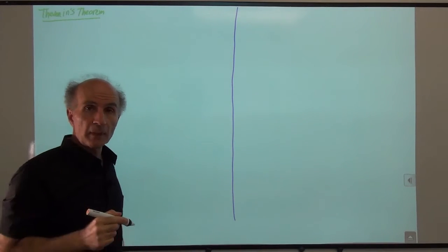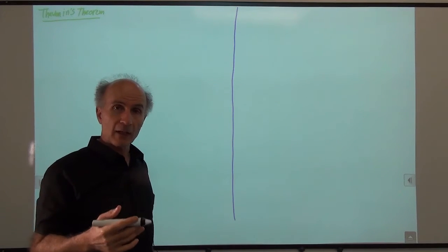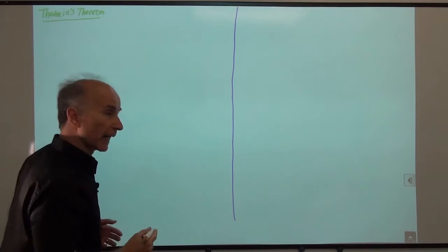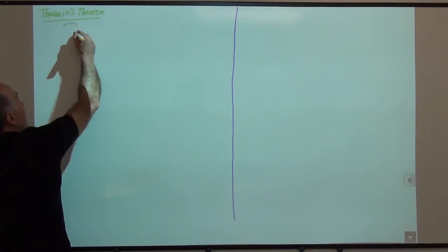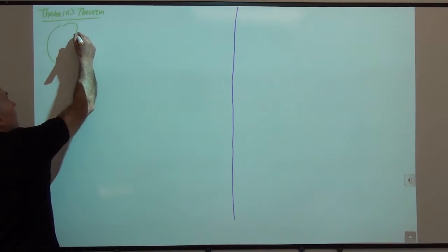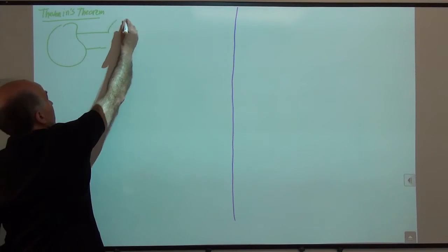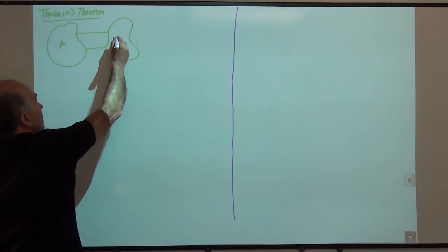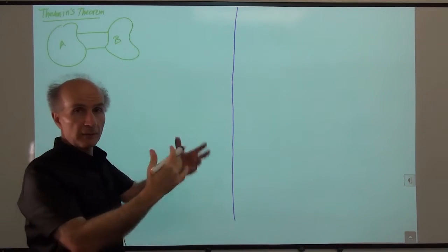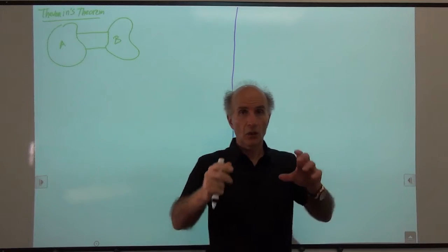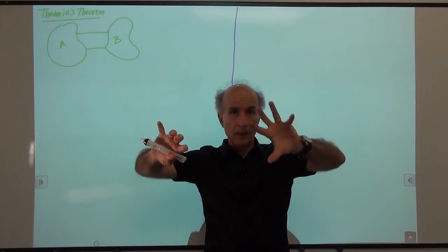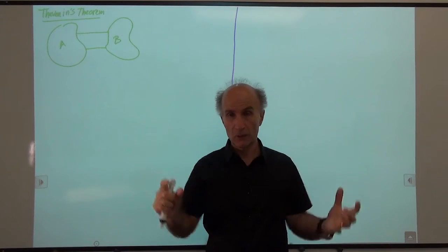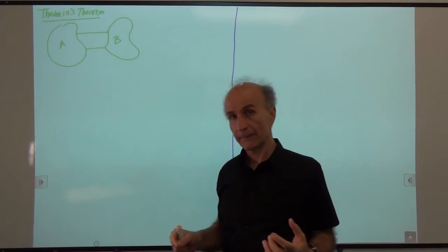So Thevenin's theorem is a principle that allows us to simplify a big chunk of a circuit. And here's how it goes. Suppose I have two pieces of a circuit that are connected by only two wires, so A and B. So any of the circuits that we have analyzed so far, right, you can just always stretch the circuit so that you have one piece here, and there are only two wires connecting these two pieces. All right?